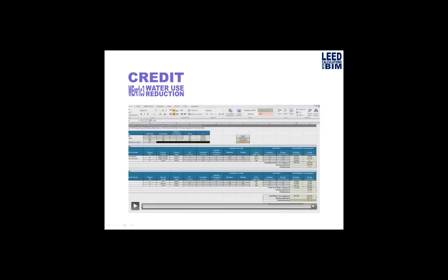So we have a sense where you're storing the information about the user group per fixture. Wait, I'm sorry. The information of which user group it is, you store this per fixture, not by room or area? No, it's per fixture. You're scheduling the fixtures for this. Does it create a higher level of human error possibilities where they just put the wrong fixture? Of course. Is it possible to maybe associate that information with the room or the area and then set it all off there? Well, then you have to create a room schedule because you can't mix that into one Revit schedule.